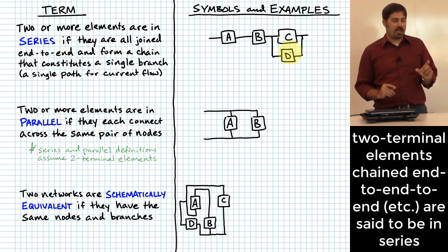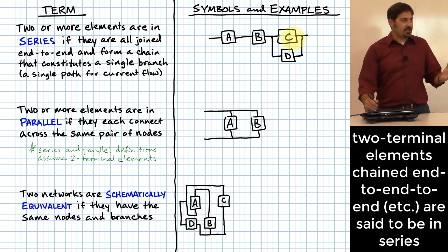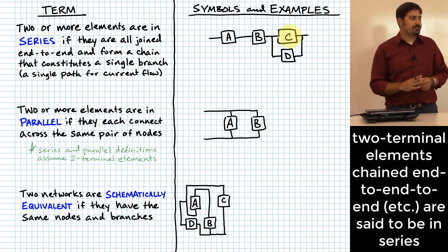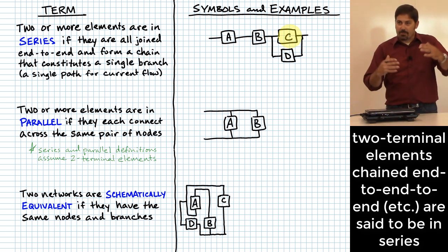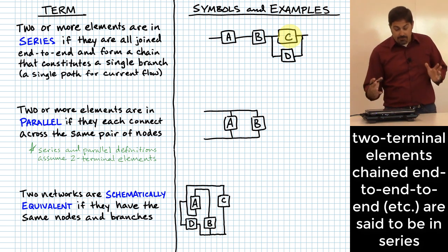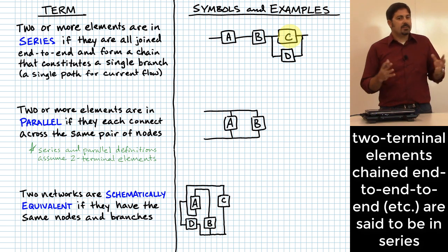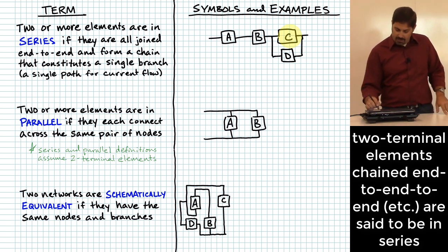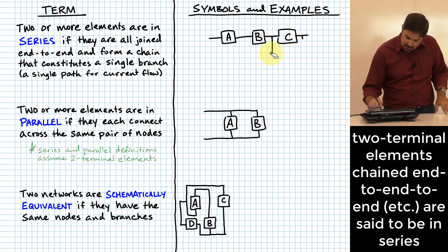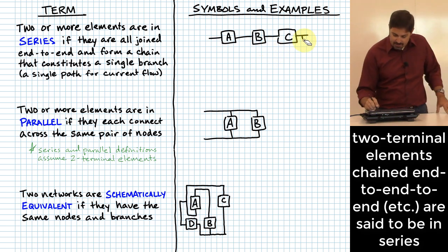That's a big assumption that we haven't gotten to yet, because these are general elements, right? Like, you can't necessarily assume automatically that you're going to be able to combine, let's say, a voltage source with an inductor, right? Like, that would be a strong assumption that you might have there, that you might be able to combine those together. So if they are combinable, then what you're saying is an accurate statement. They just might not be. Okay, so I'm going to erase those to not make it ambiguous. That was a what-if question.